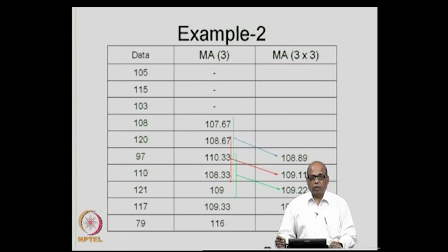If you have data on monthly stream flows, for example, this kind of method may not work well, because monthly stream flows exhibit a significant periodicity, especially in monsoon climates like ours, where June month flow is serially correlated with May month flow or the June month of the previous year and so on. So, there may be significant periodicities in the data. When you have significant periodicities or any significant deterministic components other than the mean, then these methods will not work well.